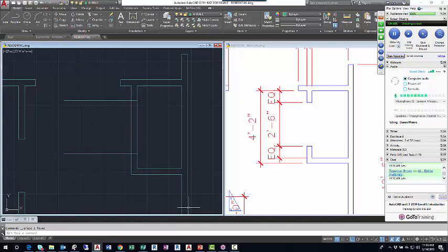So what was that? How many steps was that? Step one, I drew the line from the midpoint with ortho on, and then I used the offset. It was like three or four steps to create that. But it allows me to utilize AutoCAD to get the accuracy I need to place that opening where I want. And then it's trim, enter. I usually make the opening first, and then cut away the cutting edges, the excess, escape, and save.